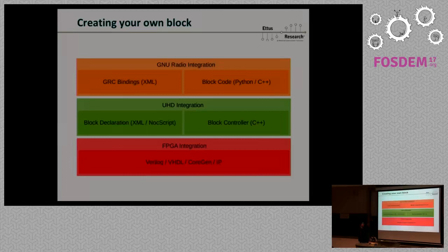So basically, apart from that, the orange spot is what you will know until now what your module did. It's going to create a lot of files that are going to describe the block as is. The XML is the one that you want to modify because if you have more inputs or more outputs, you have to tell GNU Radio.